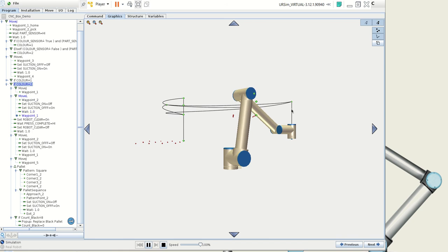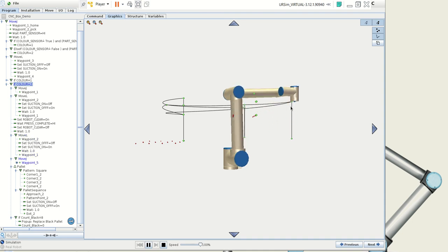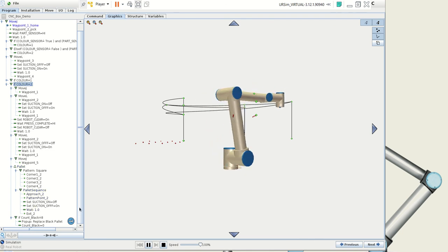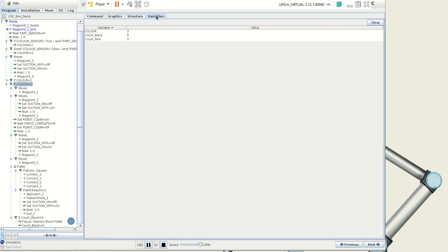Again, it does this little interface with a separate machine, to make sure the part gets drilled or pressed or whatever you want to think it is. And then it brings it round, pops it off. That should equal 12 now. Or is it? Oh, we didn't get our pop-up. That has actually replaced it to 0. We probably have to move this if command in a little bit closer with the palletizing sequence, because it actually resets before, so I have to move the position of that.